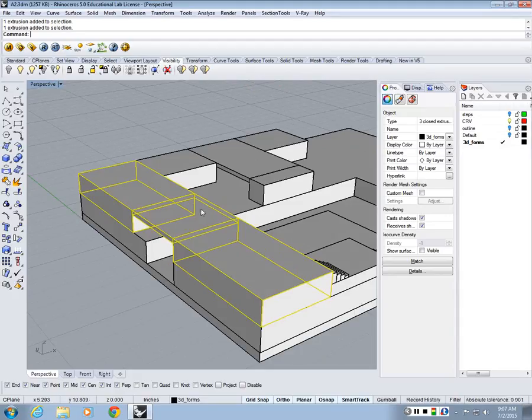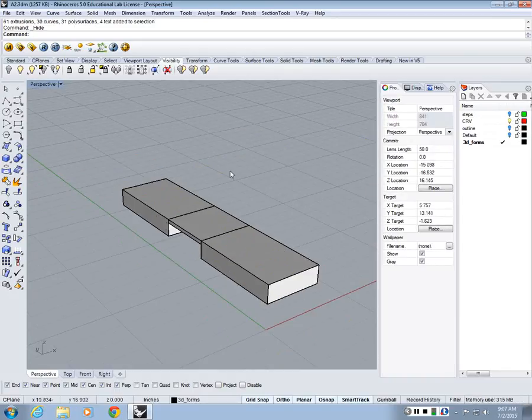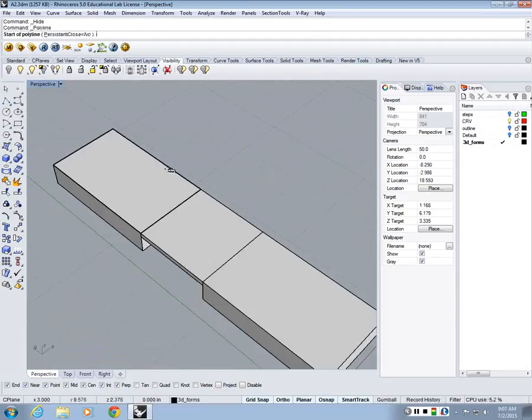So it will isolate only those 3 solids. If I press that, it will temporarily isolate my selection, so that now it will be easier, because now I can draft on it. But I want you to still be precise. So if you're starting from here, let's say 3 inches, then go this way.